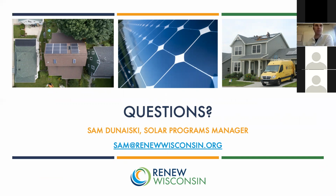Yeah, actually, a couple of questions there. So first of all, our solar contractors do work very closely with some roofing contractors too, people who specialize in roof repair and re-roofing. If you were going to start out with a brand new roof and a new house, ideally you want to do a standing seam metal roof. That's just the easiest because the panels and the racking mechanisms for the panels can attach very easily. There's just some kind of C-clamps that attach to the seams, and then the wires get routed underneath that and then go into the house along the side, so they don't even have to make a penetration in the roof if you have a standing seam metal roof.